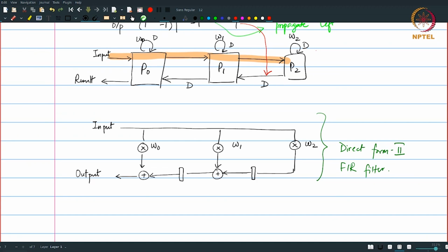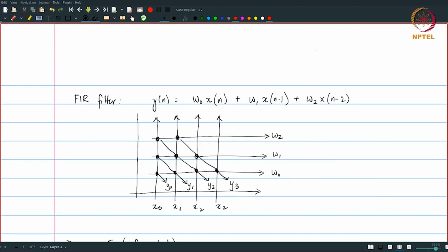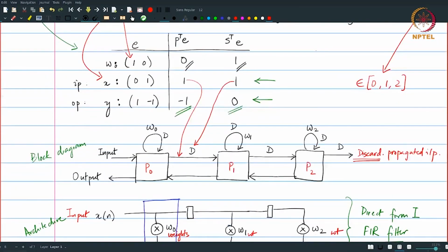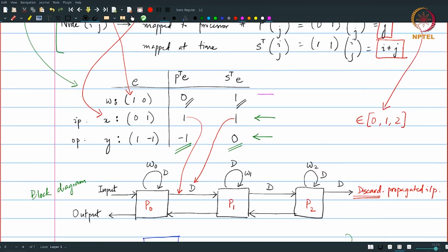Now, what are the differences between these two architectures? In the previous architecture, we would normally say that the weights are remaining stationary, meaning that the weights remain on the same processor from one clock cycle to the next. The inputs propagate or move, and the output also moves, but in a special way, meaning that it is basically broadcast. What's the difference between move and broadcast?